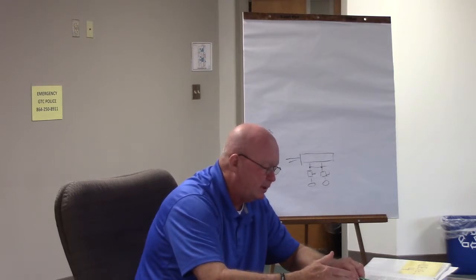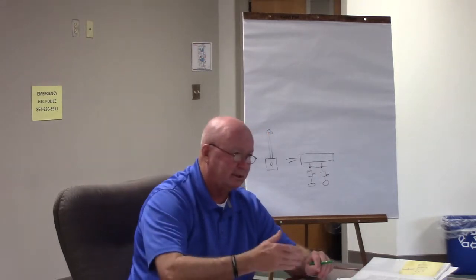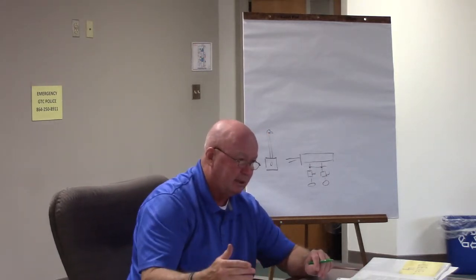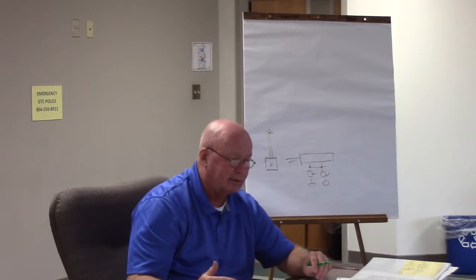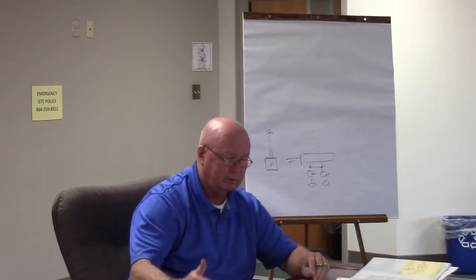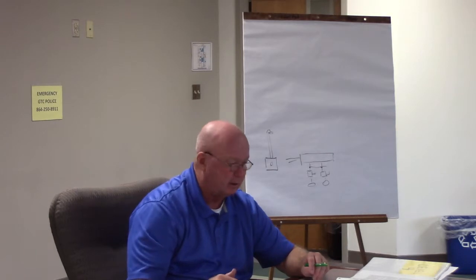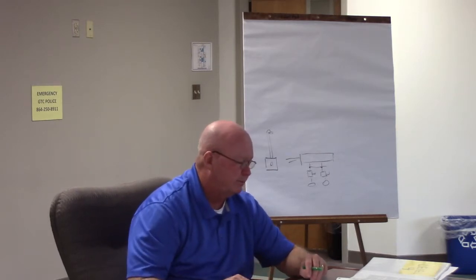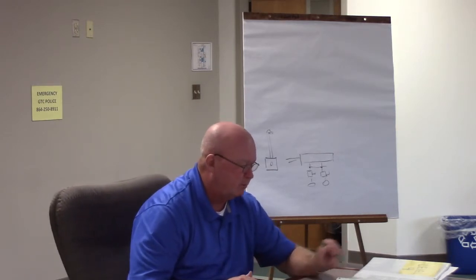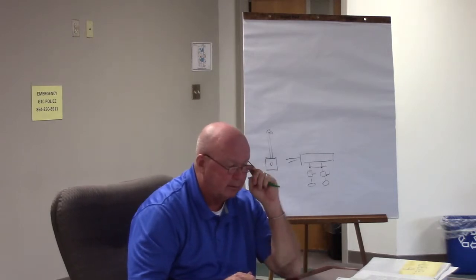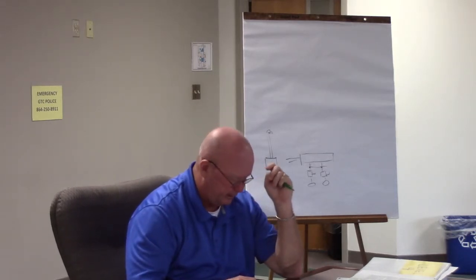When derating this conductor, the ampacity will be 150 because this is the one time you can actually use the actual type of wire insulation it is, and therefore on THHN you can use the 90 degree column, which helps. So I think that's an important paragraph right there. I think I told y'all to highlight that. All right.